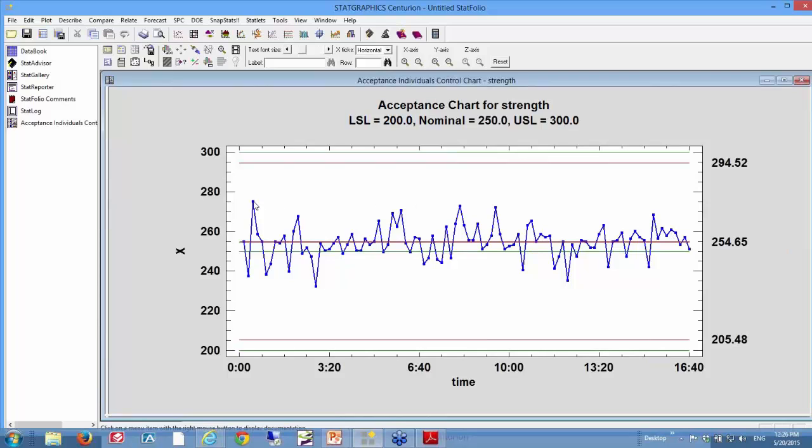So just because I have one point here that happens to be within those control limits, it's not like taking a full sample from the batch and making some statement about meeting the specification. Instead, it's meant typically to be used in real time to monitor the process and give you a heads up if the data that you've gotten are too close to the specification limits.